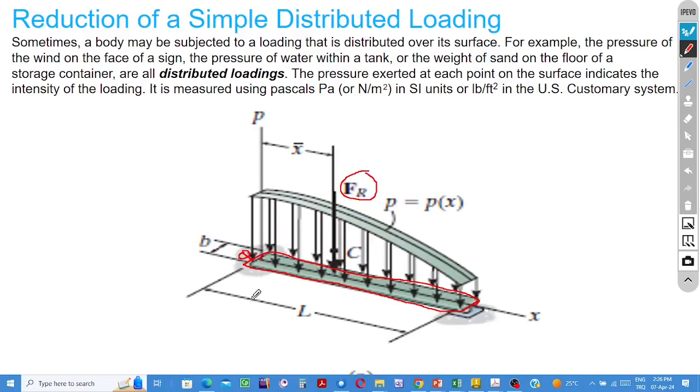But in doing this, we need to consider the rotation effects of the components of the given distributed load system. You know, if the forces are not passing through the same point, not concurrent, then they can set not only a translation effect onto the bodies, but also rotation effects.